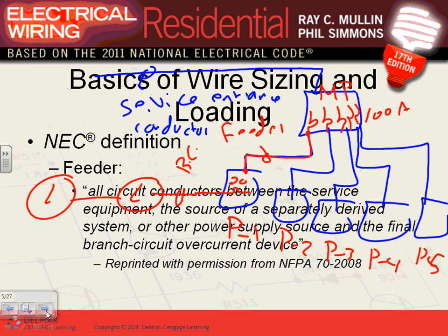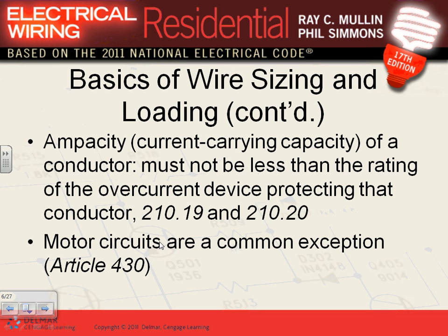Okay, so that's another thing that we need to keep in mind. Load. When we size the conductors, I'm going to walk you through Table 310.15(B)(16), which changed its name after it got married. I'll walk you through how to use it, but generally speaking, you cannot load a conductor with more current than the conductor is rated for. The current carrying capacity of a conductor must not be less than the rating of the overcurrent protection device. We will do this one in detail.